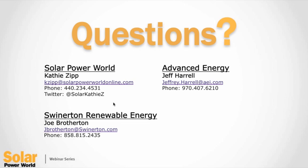All right. Joe, someone's wondering, what is stick building? They are not familiar with that term and heard you mention it. Sure. Well, the way we define stick building is going to dig a hole, pour concrete, bring the conduit in ourselves, land the inverters, land the switchgear, land the transformers all on one pad ourselves, versus going through inverter manufacturers where they deliver a fully integrated solution.